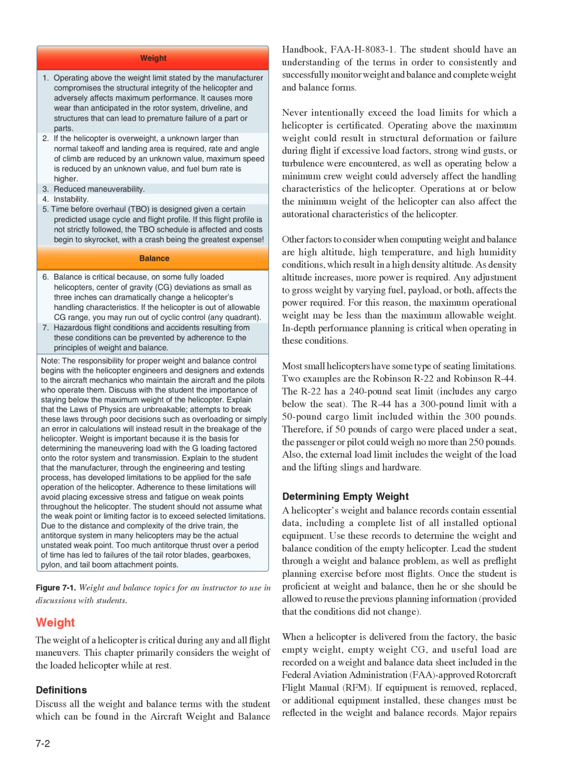Never intentionally exceed the load limits for which a helicopter is certificated. Operating above the maximum weight could result in structural deformation or failure during flight if excessive load factors, strong wind gusts, or turbulence were encountered. Operating below a minimum crew weight could adversely affect the handling characteristics of the helicopter. Operations at or below the minimum weight of the helicopter can also affect the operational characteristics of the helicopter.